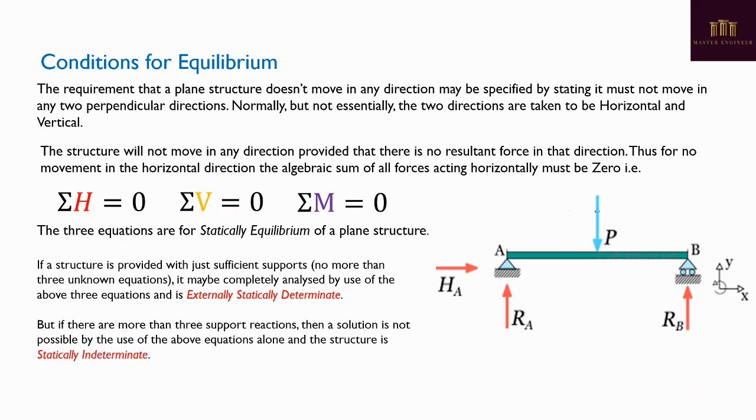But if there are more than three support reactions, then a solution is not possible by the use of the above equations alone, and the structure is statically indeterminate. In other words, if you have more than three unknowns, then we cannot use these three equations.